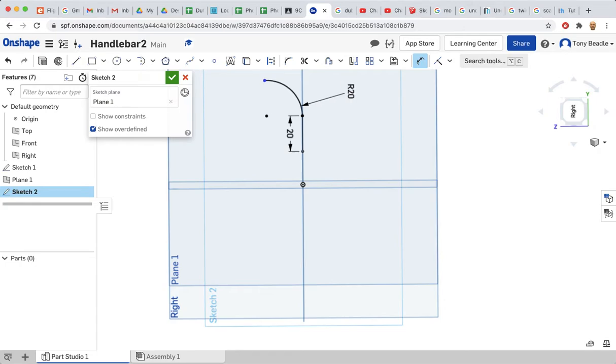Okay. Now, then take my straight line tool, click on that, drag along. Oh, now it's going slightly funny here. I want to make sure I'm actually horizontal. There. Okay, that's fine there. We'll give a dimension of 20 on that. Now, in order to make sure these two actually join up correctly, I'm going to add a constraint to this.